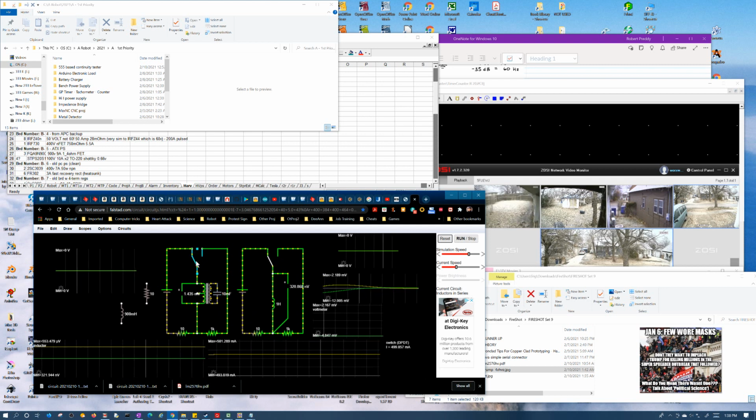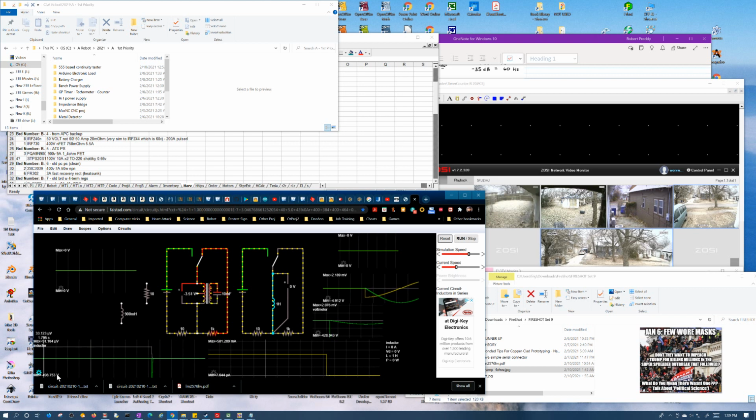But at any rate, let's go ahead and dump this charge because the field is fully charged up. Now you can see the current just plummeted here. Much the same over here. The current dropped precipitously, and you can see the voltage is really high in this circuit when we discharged it. But note it's going through a 1K resistor versus a 10 ohm resistor to charge it. So that's something to keep in mind.